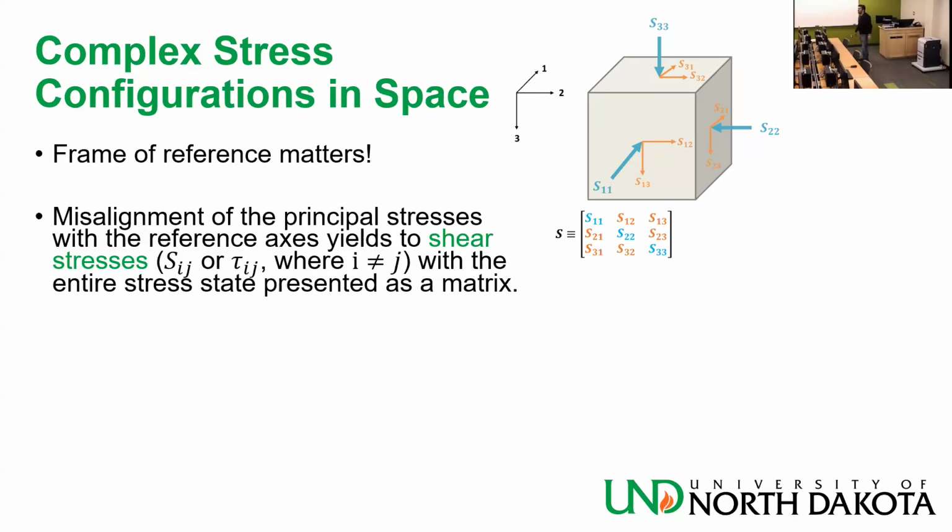If all the orange shear stresses become zero, what you have in the middle... as you are rotating that cube, the whole tensor, all 9 values are changing, until you get that perfect direction, perfect alignment, where all the orange values are zero, and the blue values that remain, called the principal values, are going to be the principal stresses.